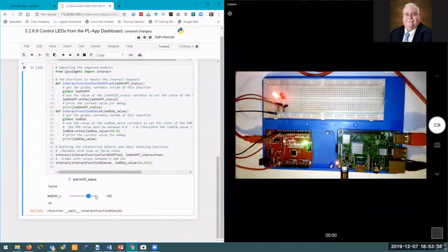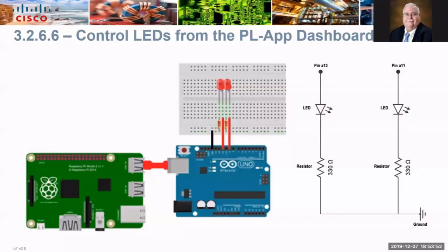Troubleshooting steps to keep in mind: Python program coded incorrectly, circuit errors, or serial connection issues will keep the lab from working correctly. To extend this lab, challenge your students to change the code so you can turn on, off and dim the same LED.